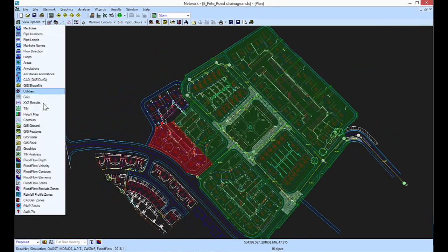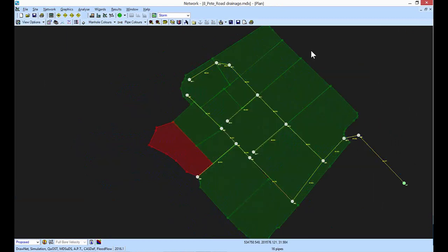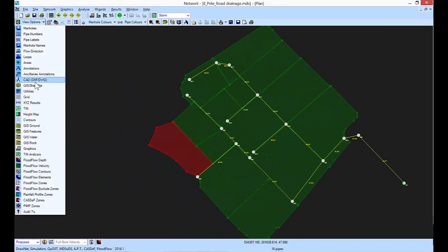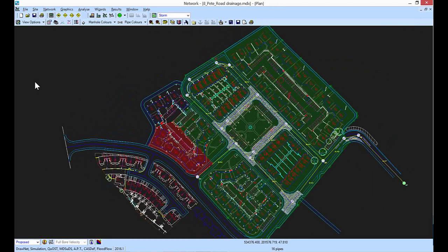I could even switch off the CAD drawing, and you can see that there's an area missing there. So it's helping us with our QA processes to enable us to identify whether there's any error within our design or not. We've missed out any kind of cul-de-sacs or areas from the project. So having designed the drainage network, yes, we could simulate, test, add in flow controls, etc.